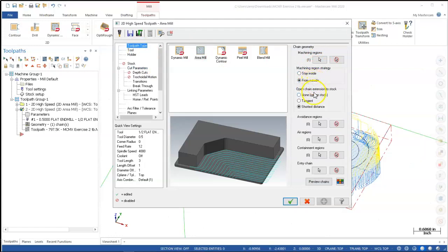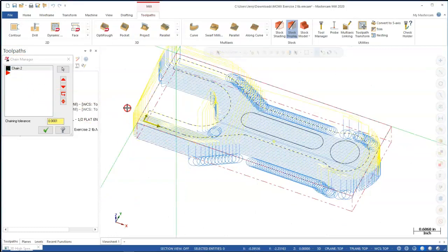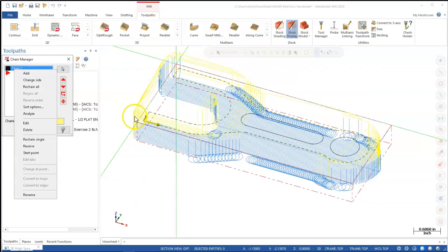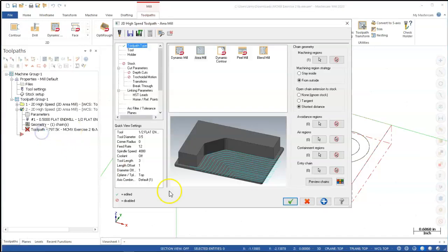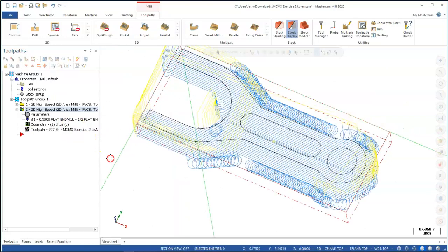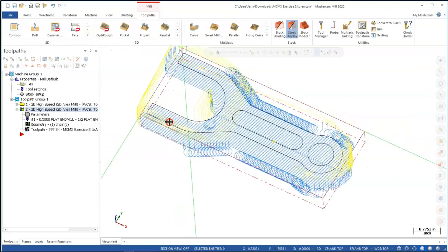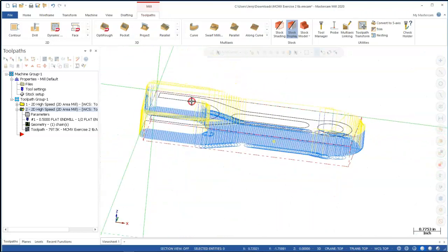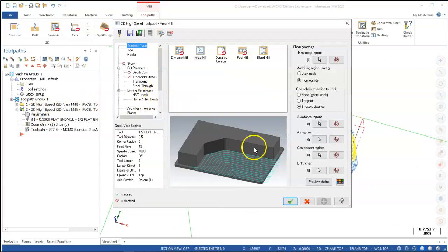Machine strategy from outside, shortest distance. And there's the direction. All right, so my arrow's to the interior. And if we can change the side, put it to the exterior. Then when it makes its approach from the outside, I'm hoping this gives me the cut. No, still found its way in. And then the cuts are coming in on that little ramp. All right, so one more.